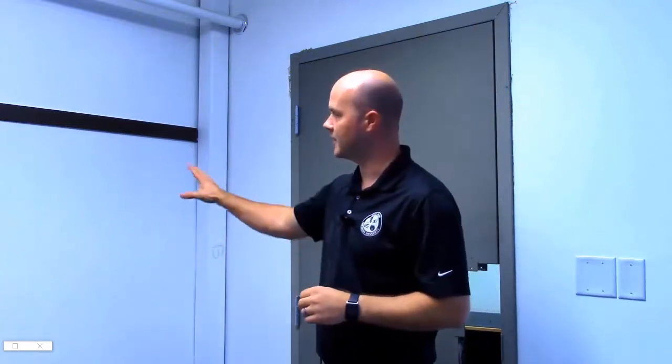And that's within tolerance. So very easily, very quickly, I was able to get this closer into a proper closing speed. We have a very nice cushion back check, so we don't damage a window, a wall, a picture, or something like that on the other side. And I did not have to open and close the door 100 times to get it to that tolerance.